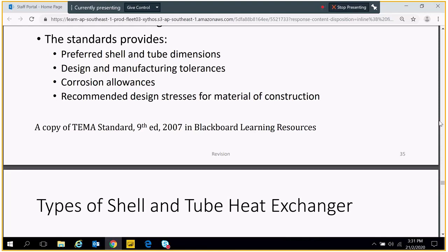Even for a strainer, you can use the L over D. But again, you need to be careful. Sometimes the questions for pressure drop across a condenser or strainer are in terms of Pascal. So are you able to change it to joule per kilogram? This is where you need to remember the format. The format for the Darcy equation is in terms of joule per kilogram, in terms of meter as a head loss, and also in terms of Pascal. So you need to memorize these 3 different formats.